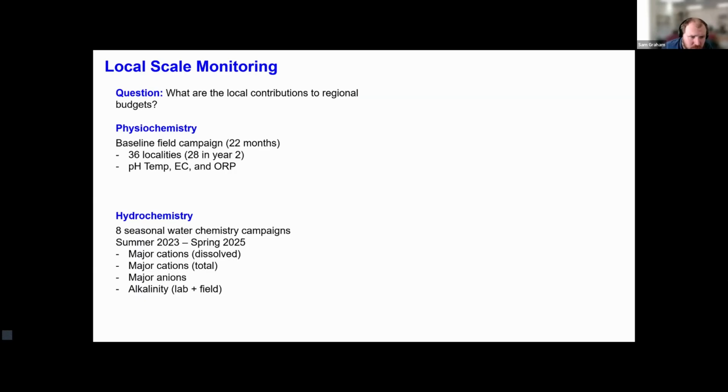So the last thing I'm going to quickly talk about is, to build all this, we need to understand how the flow in the rivers is behaving. One of the simple ways we can do this is to assume that where you haven't got a flow gauge, the flow at that point is going to be proportional to the area of the catchment at that ungauged point relative to a gauged point.